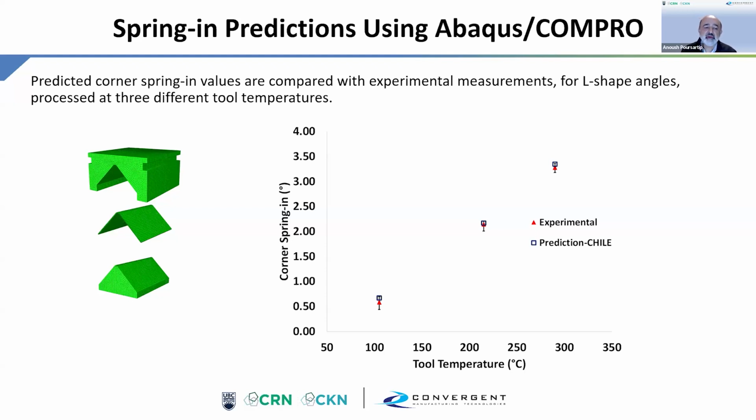Based on that, what's my modulus? What's my CTE? How much crystallization have I got? And it calculates a stress at every point, which gets integrated over the whole cycle. That residual stress, the moment you take the part off the tool, makes the part distort. Some of it stays locked in, but that which is relieved gives you the spring-in.